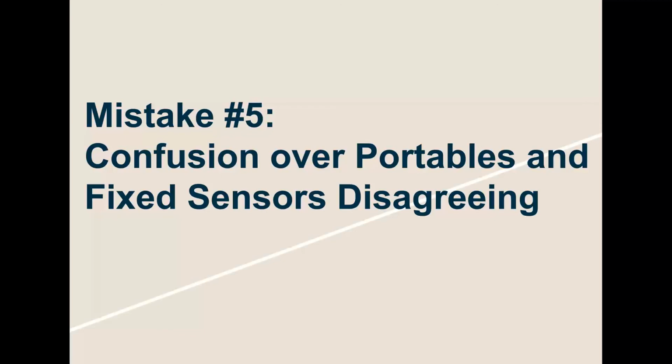Depending on the type of sensor that you're using, it could have a negative effect or a positive effect. So all those things have to be understood in order to say, okay, one really is mismatching from the other. And if all the calibrations have been done correctly, all the correct equipment has been used, all the correct calibration gas has been used, then the issue might be that your fixed gas detector is calibrating with way too much dry air. We might want to introduce some humidity into the sample, or B, there's a cross sensitivity difference, right?